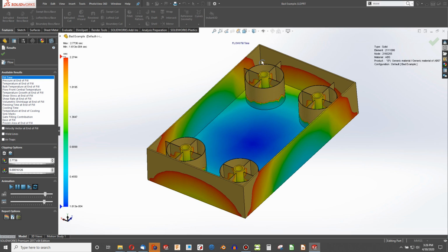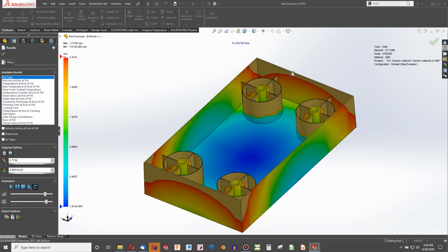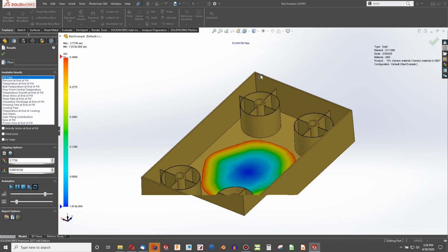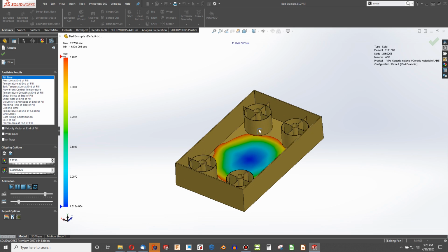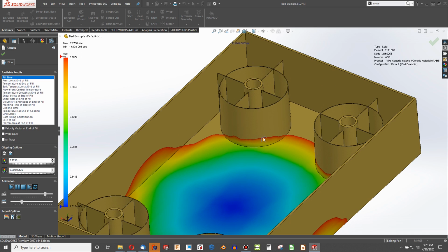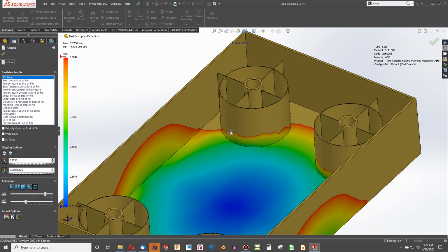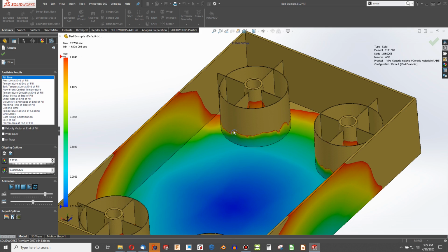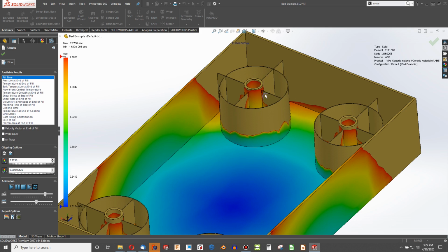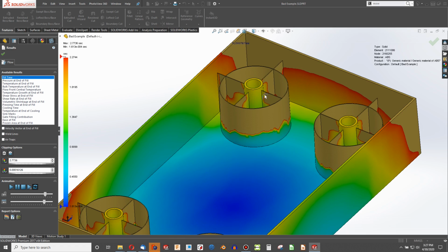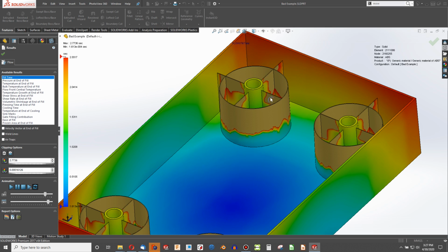But what's interesting is as everything else gets filled up, the very last thing to get full are these rib features. So you have plastic that does not flow well because the rib is too thin, so we don't flow very well right here. And we end up freezing, right? The plastic ends up hardening, and we can't fill it the rest of the way. This is a little bit more thick and flows a little bit better, so we can fill up this center area. But again, we get flow front hesitation and largely stop off.